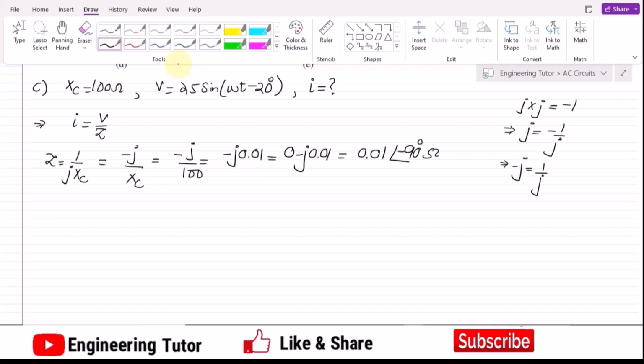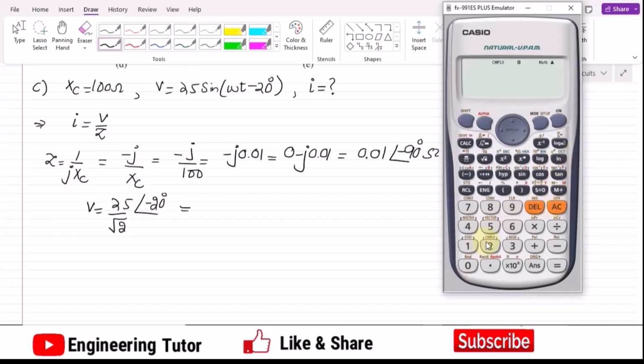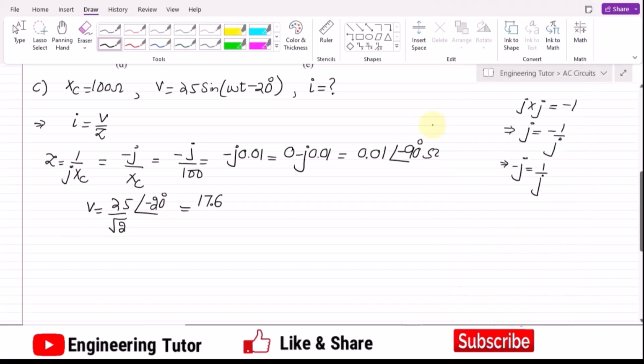What is the value of V? In order to calculate the value of V, we have this peak value. To convert it into the RMS value, I have to divide it by the square root of 2, and write the angle here, which is minus 20 degrees. So 25 divided by square root of 2 is 17.67 or 17.68, and the angle with it is minus 20 degrees, and this is in volts.